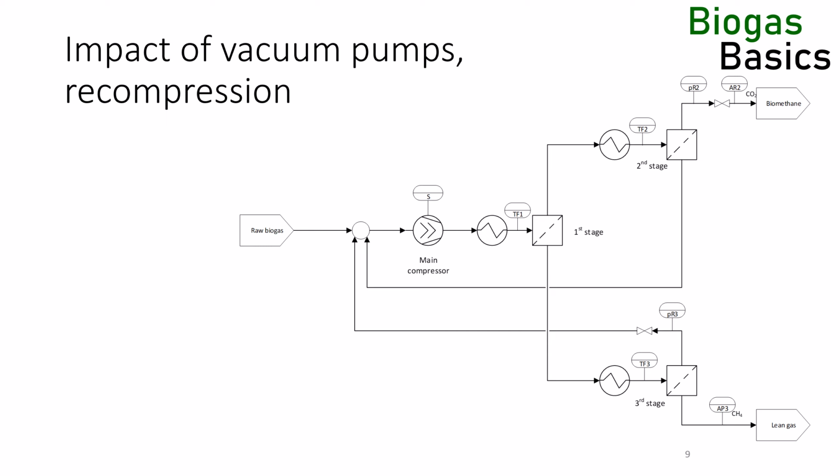If we apply a vacuum on the permeate side and lower the pressure to 0.5 bar, the pressure ratio doubles to 20. This leads to a significant improved CO2 recovery and permeate purity. The effect is not the same as increasing the retentate pressure to 10.5 bar. We can try to improve the process by installing permeate compressors on all 3 stages.